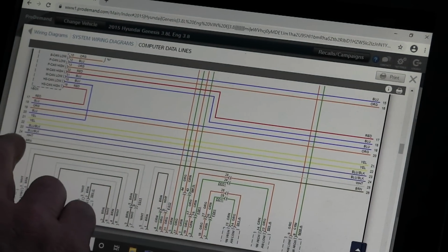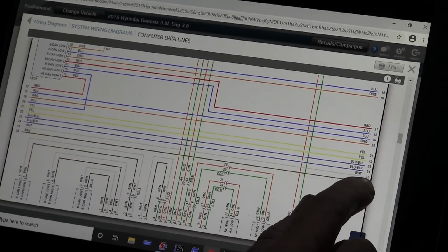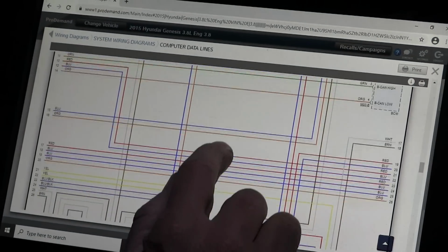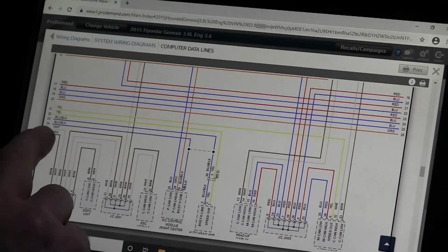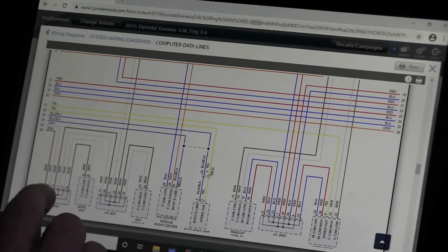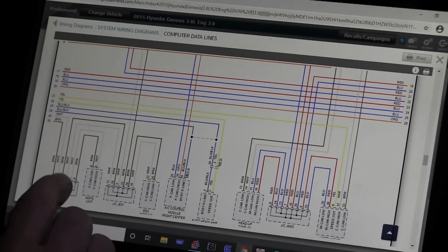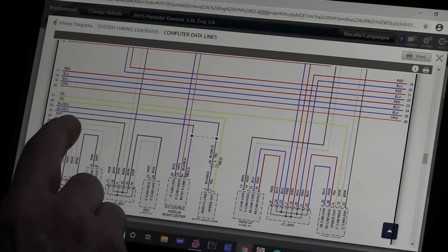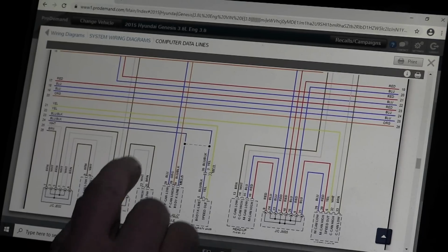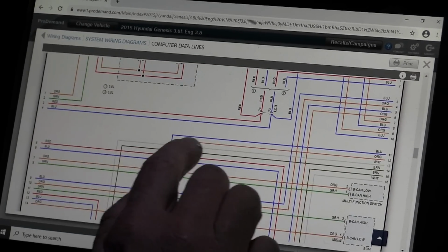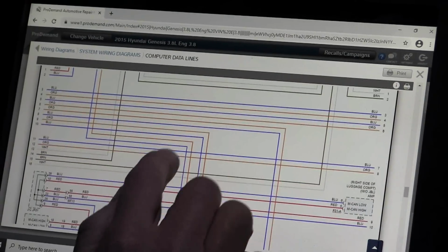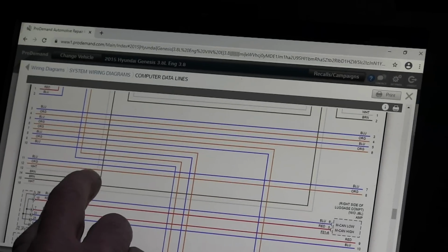So we come down over here, and that's these bus wires that come down also at the bottom, 25, 26. So let's find that. They come in right here, 25, 26, and they go into another splice pack or a CAN pack where I can diagnose this. Now out of this one, it comes up into this unit, and then they come across, and I've got another pack, but this one comes over into the ESC again, and then we come up here and we come across, and that's 13, 14.